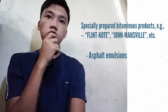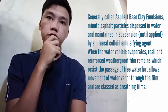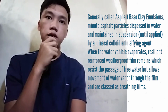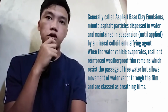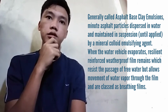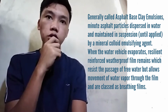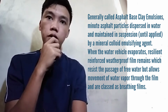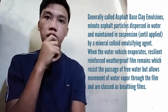And asphalt emulsion. Dry coat asphalt emulsions basically mean asphalt particles dispersed in water and maintained in suspension until applied, made with a mineral colloid emulsifying agent. When the water vehicle evaporates, a continuous reinforced weatherproof film is left which resists the passage of free water but allows movement of water vapor through the film and is classed as a breathing film.